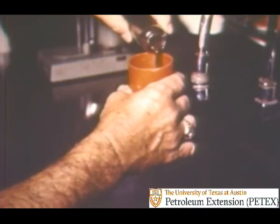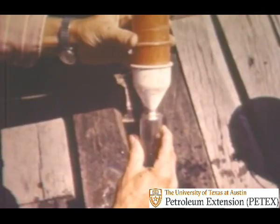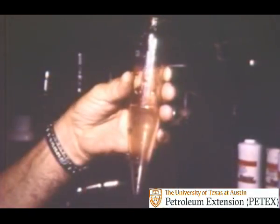Next, the sample is poured into this cylinder that has a 200 mesh screen in it. The screen traps any sand in the mud. Several washes of the tube are made to make sure all of the sand gets out of the tube and onto the screen. The orange screen container is placed in a funnel with the sand on the screen pointing down. The end of the funnel goes into the tube. The sand on the screen is washed down into the tube with water. The sand is allowed to settle in the tube, and the percent by volume of sand is read directly from the tube.